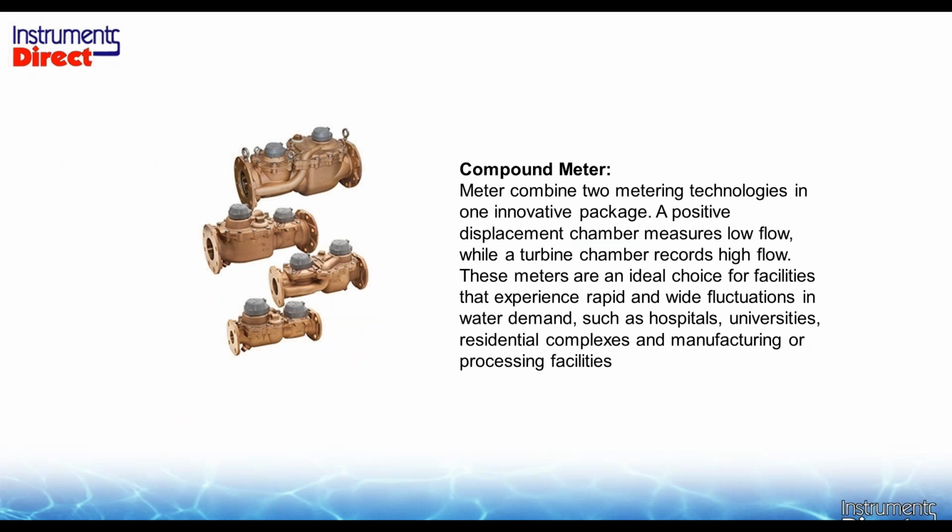So I might be able to pick up that toilet flush if I've got a 1-inch or 1/2-inch line monitoring with a traditional flow meter. But my reference meter we just talked about is an 8-inch line. So it's an apple and orange comparison. So if you're going to do a flow study and you're interested in low flow monitoring, you have to have like information. To compare against a compound meter, you can monitor the 8-inch compound meter, but it also has a sidecar, a small, usually turbine, flow meter that's monitoring a smaller line size. You won't have any ability to reference it. So that's an issue there.